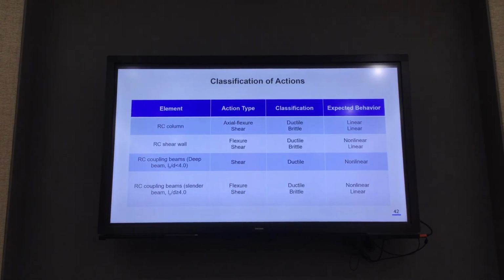So, in performance-based design, we consider the response, and based on that response, we design our building? No. Performance-based design is a check of the performance. You don't design. Actually, the term is wrong. We normally call it PBE, we don't call it PBD. It should be called performance-based evaluation, because this is not a design procedure. This is an evaluation procedure.